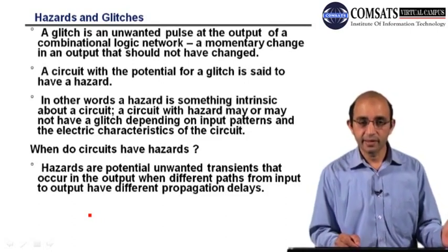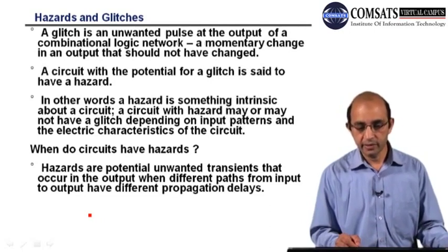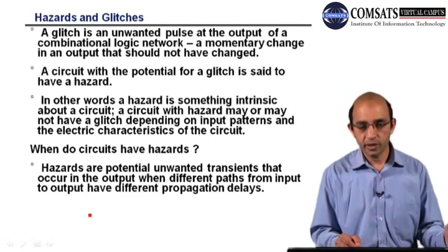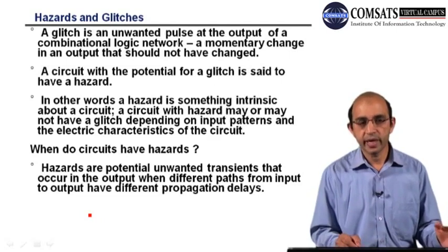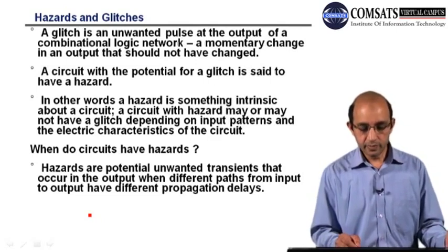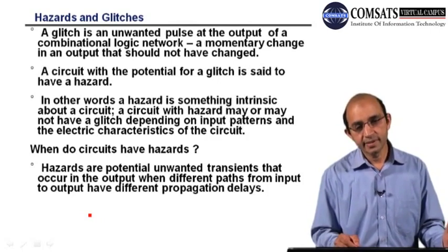A circuit that has the potential to produce a glitch, that has the potential that there can be an unwanted pulse at its output, is said to have a hazard. So when we talk about circuit analysis, a circuit with hazards may or may not have a glitch.